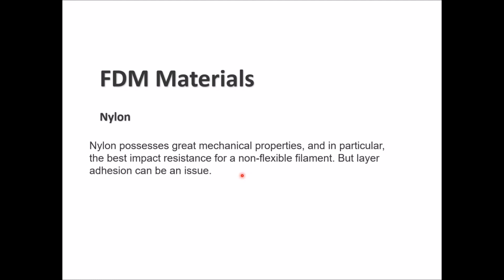If you go with nylon, nylon has good mechanical properties, and in specific a very good impact resistance, even though it is a non-flexible filament, but still having good impact resistance. However, the layer adhesion for this material is considered very low.